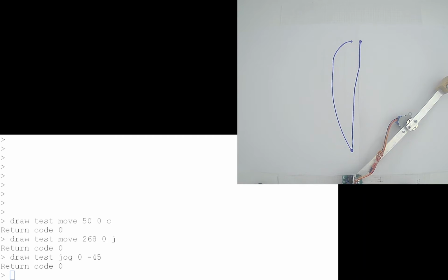By the way, when I built the arm, I made the links fairly long so I could make large moves. I thought that was good. The downside of that is the longer the links are, the more the backlash is magnified, and we're seeing the effects of that. But anyhow, in looking in Cartesian space, I think you'd agree the first line looks somewhat linear. The second one is linear in joint space, but not at all in Cartesian space.